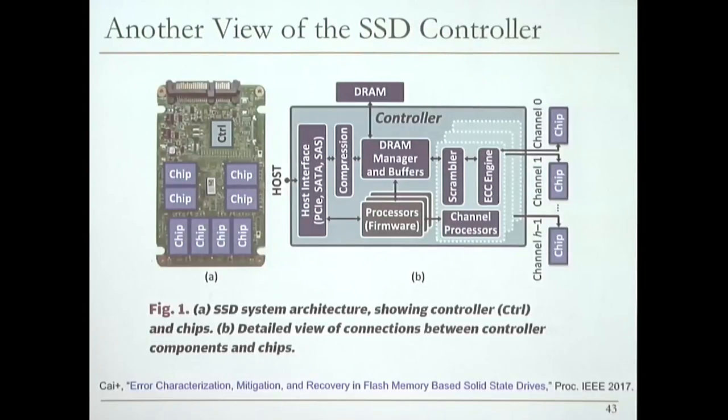That's the type of technology. In DRAM, it's becoming that way, as we've discussed earlier. But it's not at that point fully yet, although chips are incorporating ECC internally right now. So going forward, we may see similar parts in a DRAM controller as well. OK. This is just to give you an idea. We're not going to cover this in detail, and you don't need to understand all of this clearly. But this is a more complicated controller than we're going to talk about today.